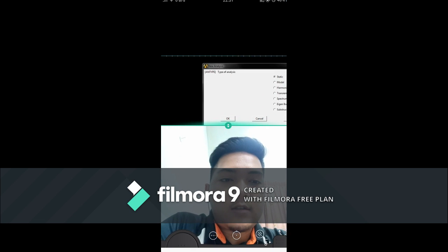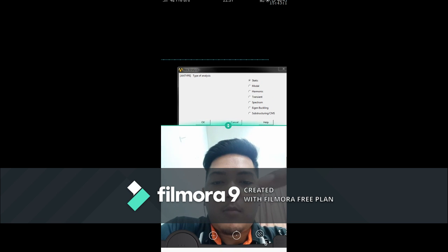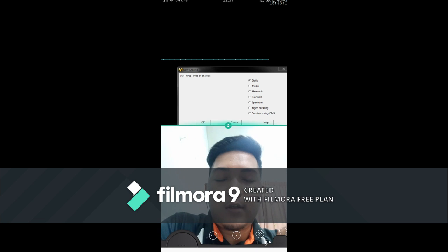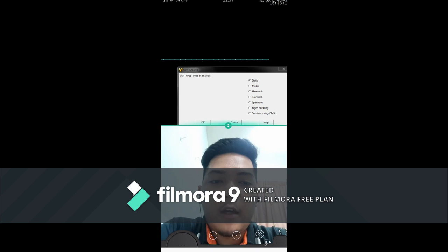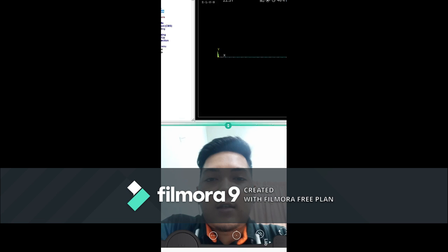Okay, hi. We will start the process by choosing the new analysis, and it will pop up the type of analysis, and we need to choose the static because we want to perform a static analysis, and it is valid for all degree of freedom, which is all DOF. Now we proceed and we just select OK, and we will proceed with the next slide.